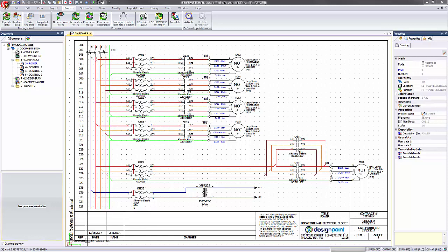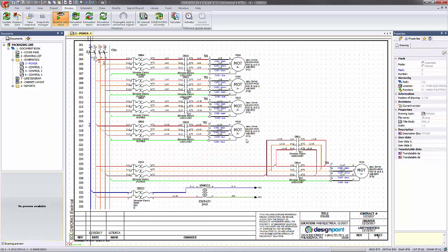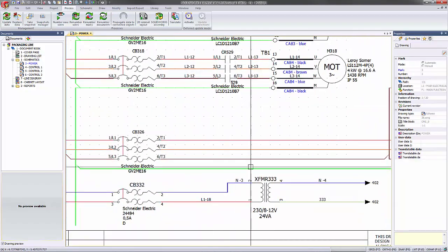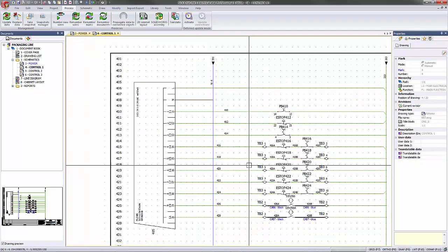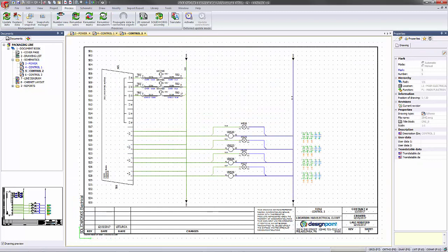All right, so now that our schematics are complete, it's time to start the documentation phase. For me, this always starts with numbering all of my wires. Just a huge manual process going through and numbering these by equipotential. In SOLIDWORKS Electrical though, it's just a matter of clicking on Number New Wires. There are predefined formulas within these wires that determine how they're actually going to be numbered. You can see all of our power lines are numbered a little bit differently than how we number our wires for control. So that's awesome. That's actually been done across the project.